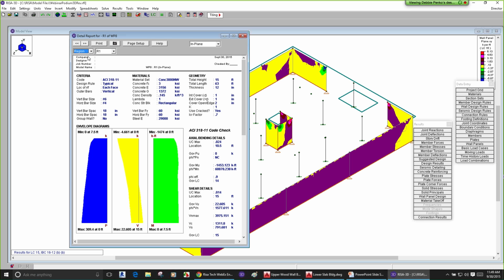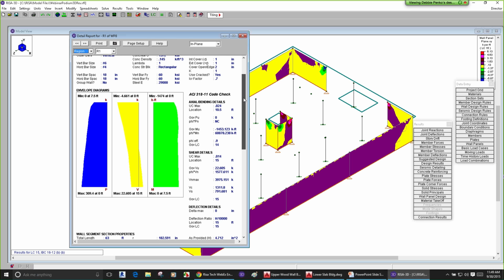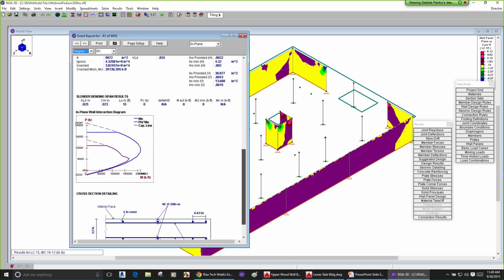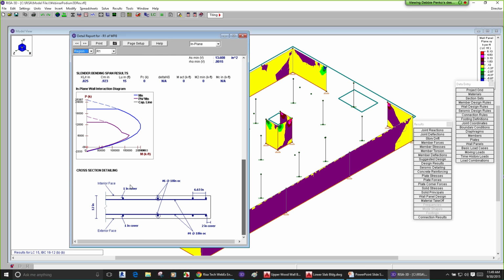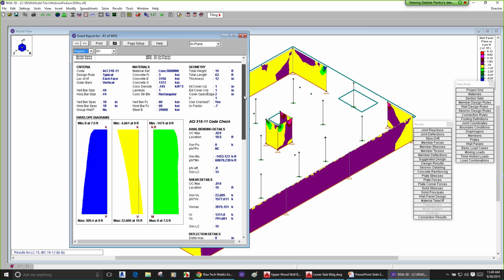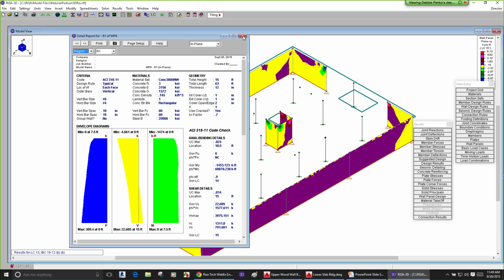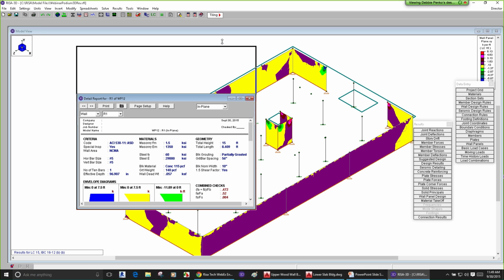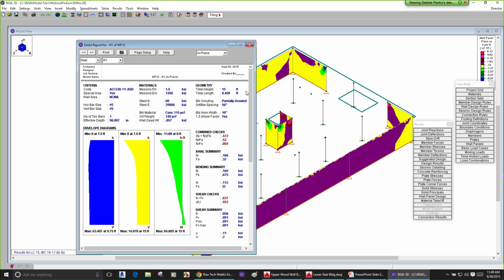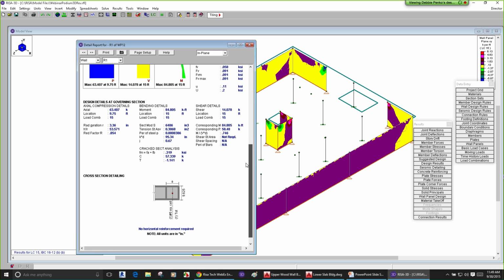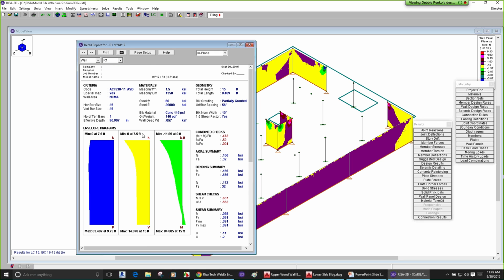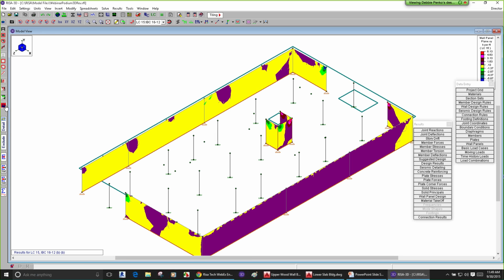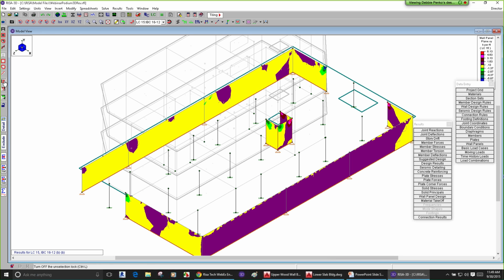So you'll always get the worst case design for your reinforcement, and you can see here that we get in-plane diagram. It starts to design all of that information for you for in-plane and out of plane. You can also see the masonry wall design as well. So masonry is being designed, calculating the in-plane and out-of-plane forces for you, and with a diagram for each envelope diagram there. On the upper structure, I'm going to unlock this upper structure and just show that for a second.